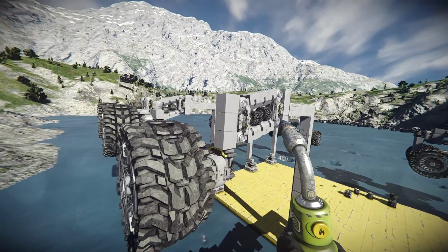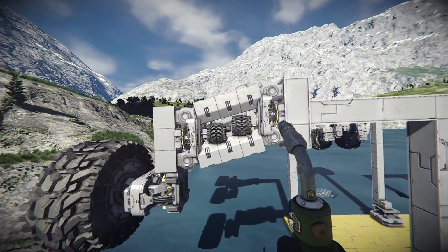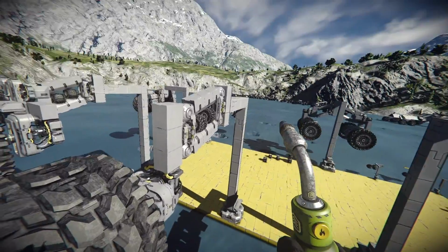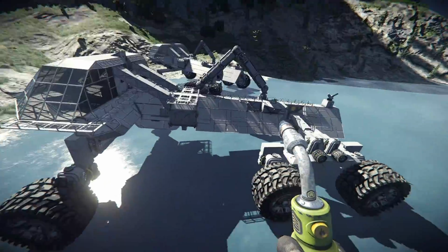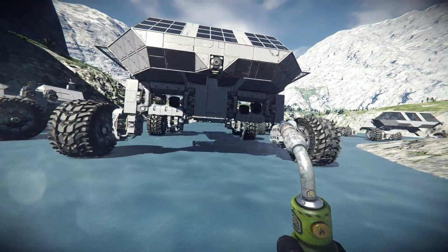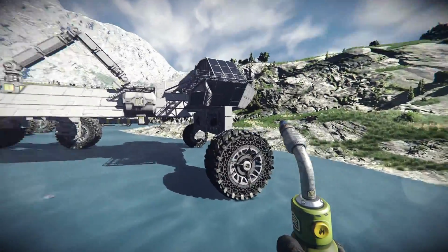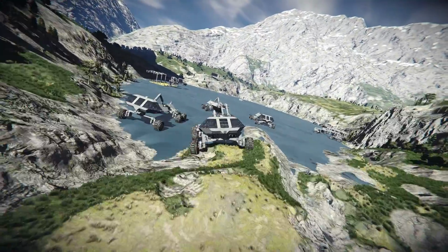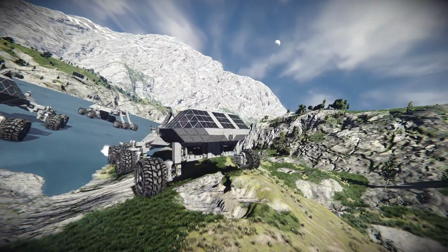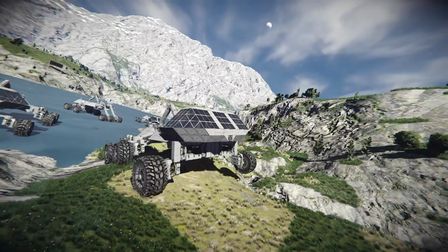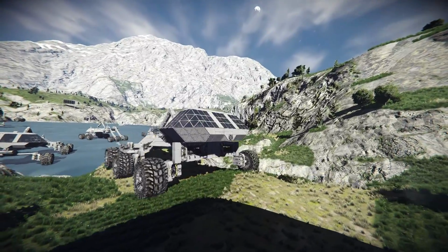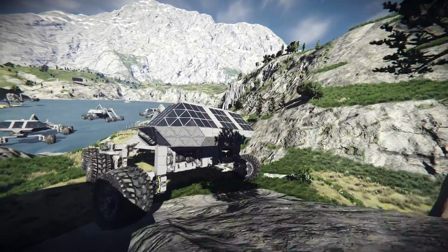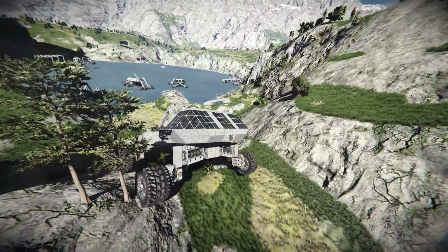The next option is basically an independent wheel that is placed on its own axis and has its own movement to be in contact with ground, and as you see, this vehicle is built on that type of wheels. So let's drive it and see how it behaves. As you see, front wheels try to be in contact with ground all the time, and it actually works not too bad, but it has kinda limited movement downward, you know?